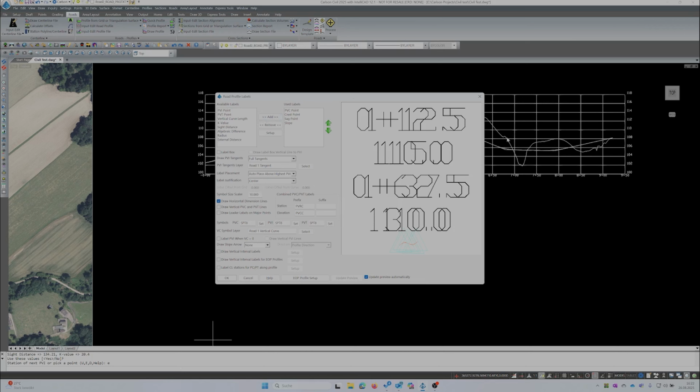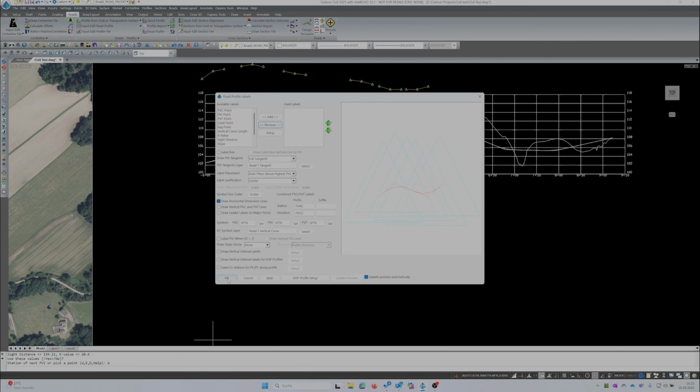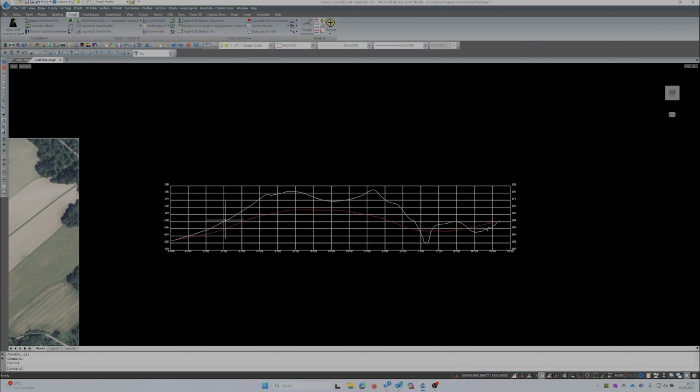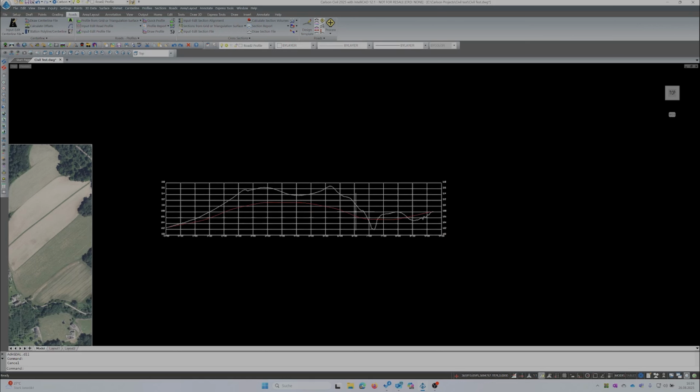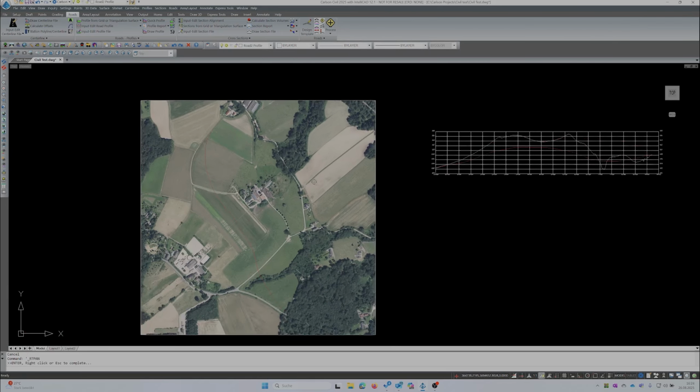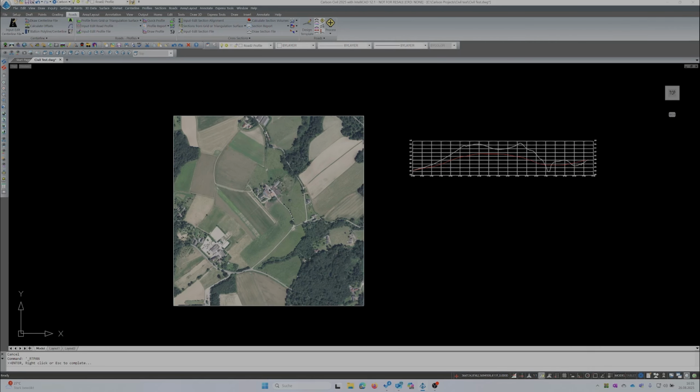So we could use some labels for our description: BC points, crest points, sec points, slopes, curve length, side distances, radius, external distance, and so on. So here we see now our original terrain. And here we see the changed elevation profile of our new road that we've just created. So there will be quite a bit of cutting and a little bit of fill. So with that being done, we can now process our road.